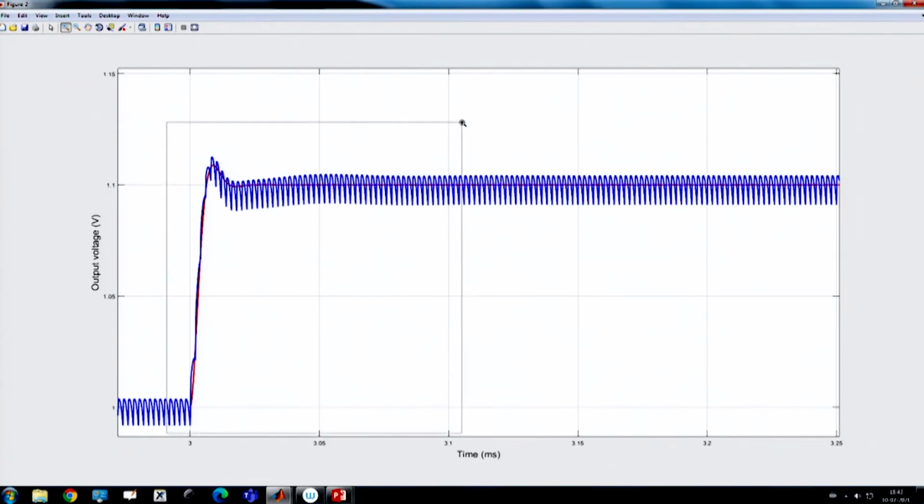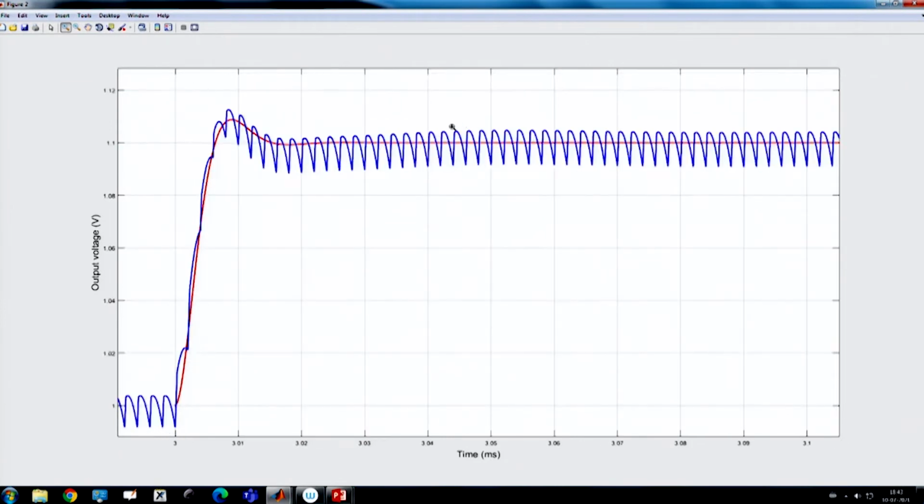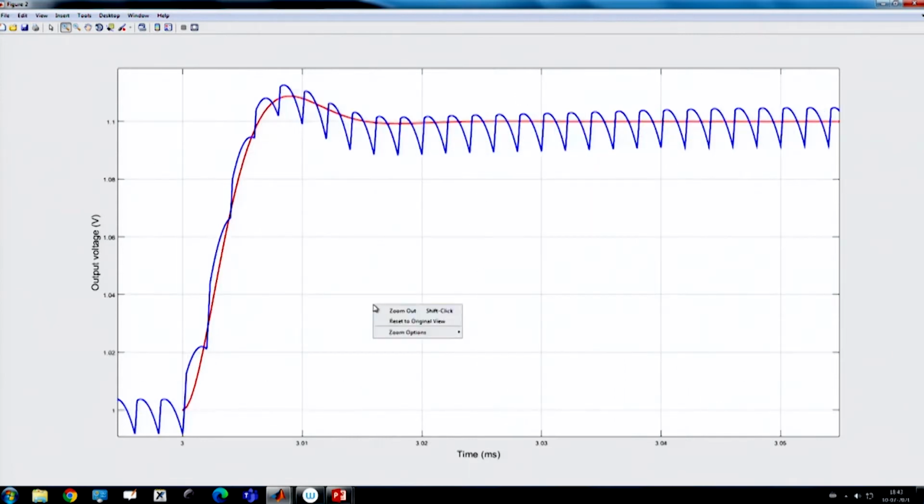So, now at 1/10 switching frequency it is matching. That means the matching also depends on ESR. For a little larger ESR, you can go up to 1/10 switching frequency and get reasonably good matching. But if we reduce ESR, then the validity of the model will get degraded even at 1/10, because we have to operate at a lower switching frequency. But what I want to say is that it is a well damped response, the closed loop performance.